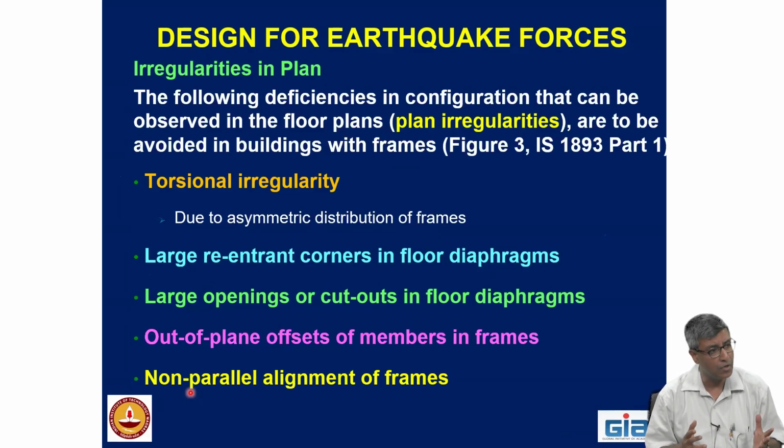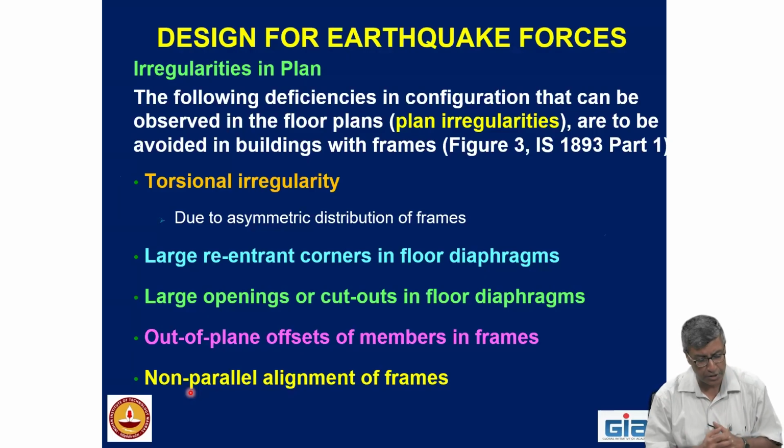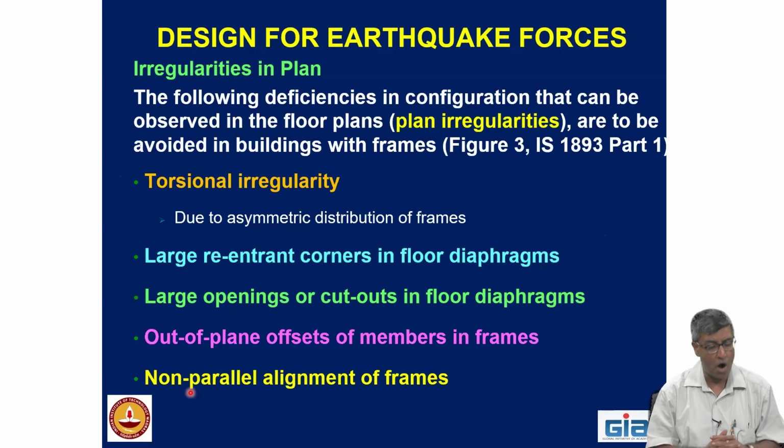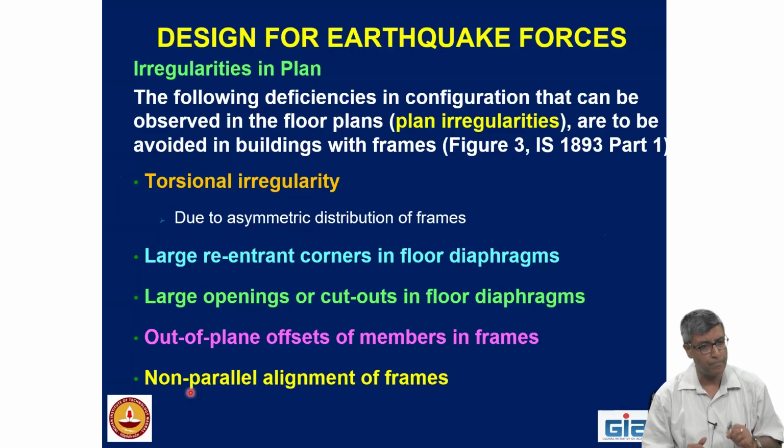It's a torsional irregularity. Today, Professor Liberato was talking about the torsional effect. If the floor diaphragm has certain corners, there will be stress concentration. If there are large openings in the diaphragms, there will be problem. Out of plane offsets of the frames, if the frames are not properly placed, or non-parallel alignment.